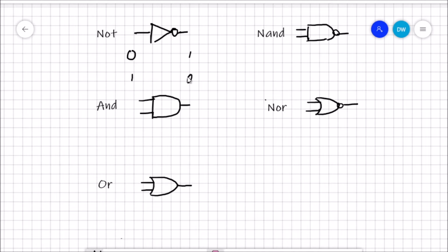In terms of electronic circuits, these lows and highs just mean voltage. So if you apply voltage here, there will be nothing over there. If you have nothing here, there will be a high voltage here. And that's pretty much it. Most basic electronic circuits are probably 5 volts. So if you apply 5 volts at this end, you get 0 here. If you apply 0 here, you get 5 here, and so on.